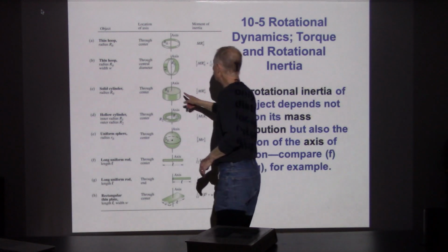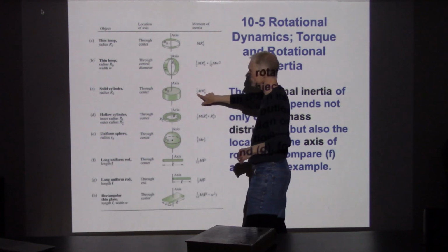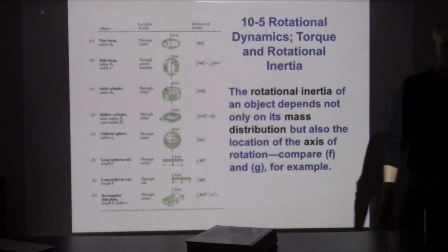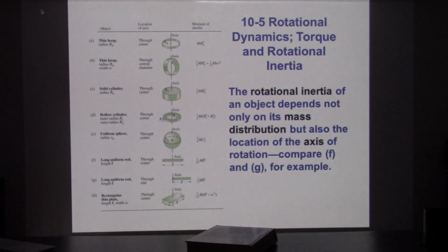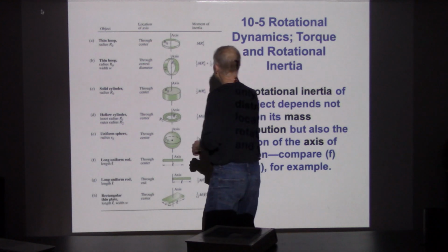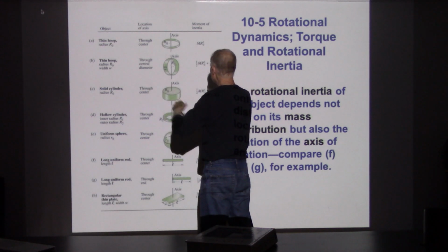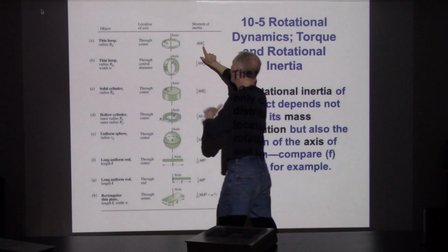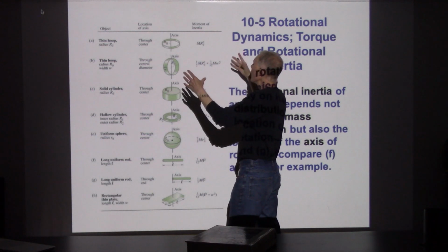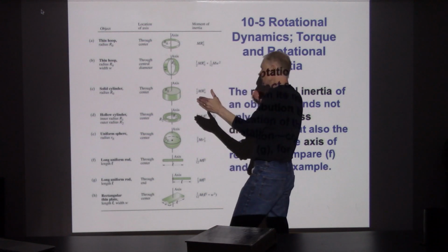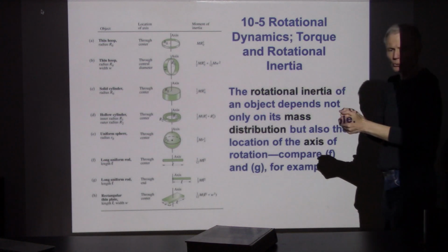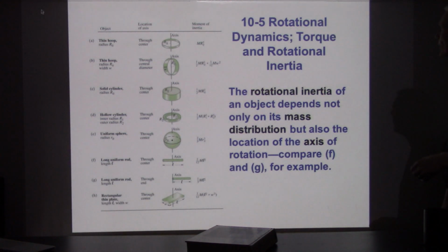And that's because this 1/2 out here is what I consider to be a shape factor. It's a factor that we can calculate using integration. What it's telling us is, on average, how close is the mass towards the center versus how much of it is spread out. In the case of the hoop, all the mass is out at R0. With the cylinder, it's a continuum. Some of the mass is really close to the axis and has almost no effect on the inertia.